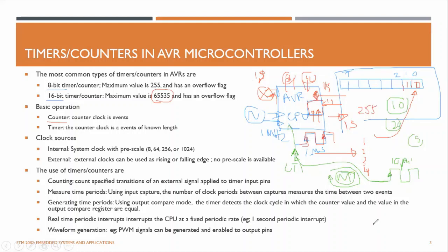Or sometimes in applications, you might be using IR sensors. Let's say you have a supermarket, and this is the entrance. So you set up an IR sensor. If a person enters through this IR sensor, it will generate a pulse, and you can give that pulse to this pin, and now the counter can be updated. So the number of people who entered this supermarket can be counted using this, right?